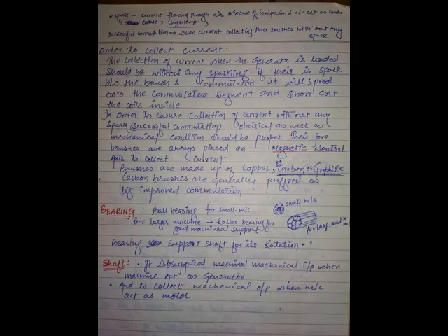This is DC of 100 volts. This is also DC of 100 volts. But this is pulsating DC containing high ripple content. This is a better DC with less ripple content. So what is the armature winding doing now? It is improving the waveform shape.